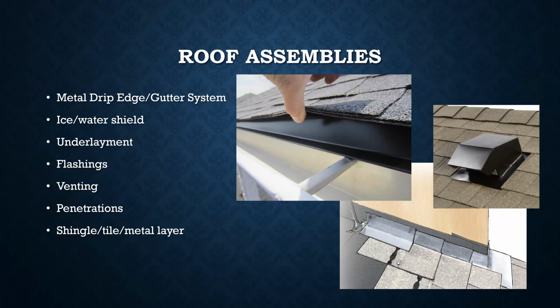And then you're going to go up the rest of the roof with all your underlayment, cover up the whole roof, make the whole roof waterproof. And then the flashings, depending on the situation, the flashing can happen as you're doing the shingles. Like in the bottom right photo, it's showing step flashing being installed up a chimney side or a wall or something like that, where you've got shingles going up. The wall flashing is installed so that if water runs down the wall, comes onto the flashing, it runs onto the next shingle instead of running down underneath the shingles. That's an example of a flashing. Those can go on before, they can go on during shingles. It depends on what the situation is and where you're flashing.